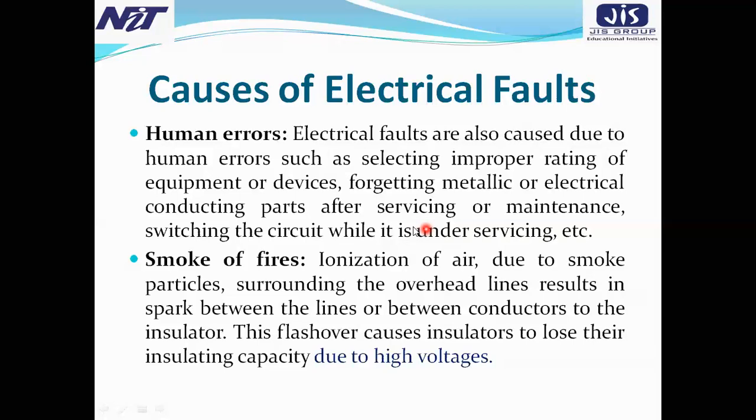So after discharging with the help of the earth stick, the engineers use the lifeline detector. If there is any charging current on that cable, the detector gives a signal that there is some current. Then discharge again. So nowadays, in most places, these devices are used to avoid human error. So human error is one of the reasons for these electrical faults.